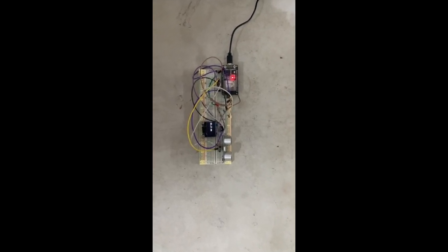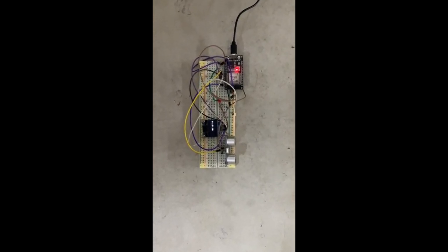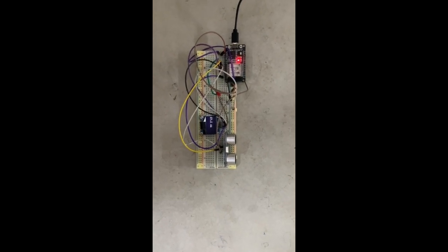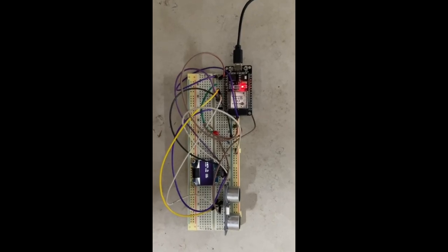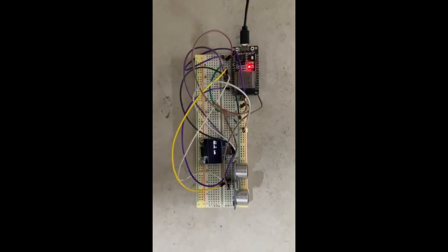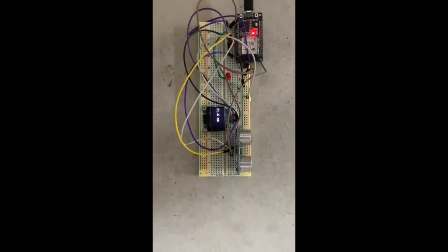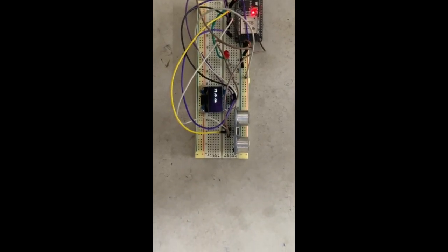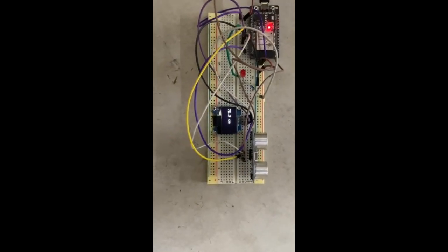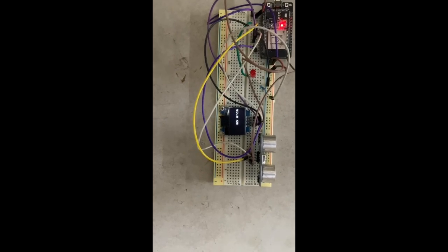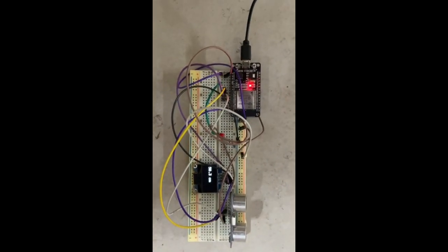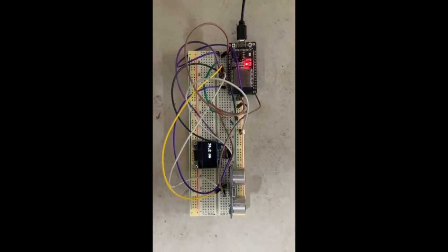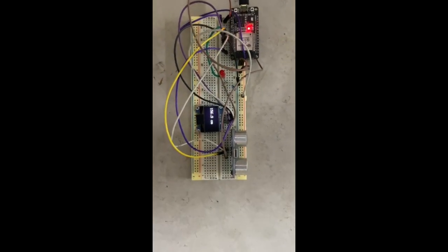So this is the hardware setup, in which we use an ESP32, ultrasonic sensor, OLED, resistor, breadboard, jumper wires, and LED. When we power up the breadboard setup, the ESP32 starts running the code. The ultrasonic sensor keeps checking if there is anything in front of it. The OLED display shows the measured distance every half second. If you move your hand or any object close to the sensor, within about 20 centimeters, the ESP32 instantly detects this and turns on the LED as a warning.